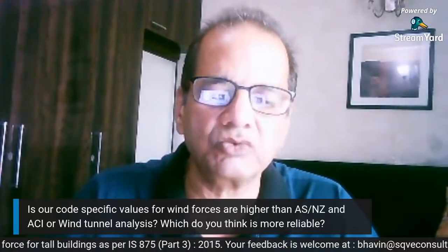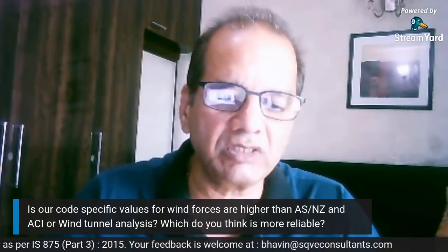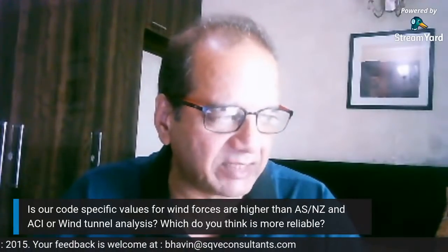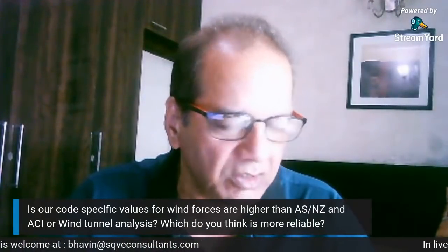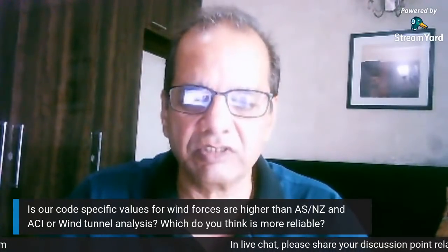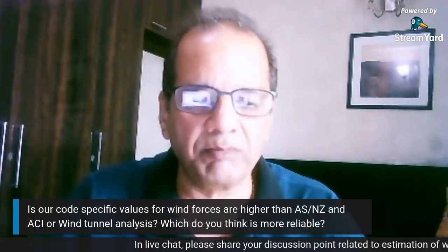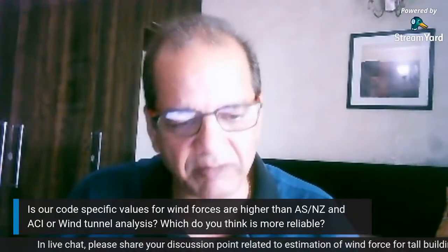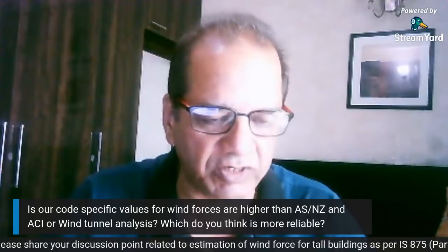The only care the user has to take is that while calculating, we are multiplying these coefficients with the design wind pressure, which is obtained based on the 3-second gust wind. So any other code to which you are comparing should also have the same 3-second gust wind pressure.